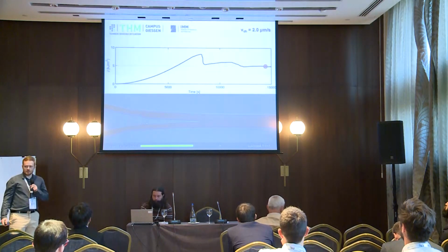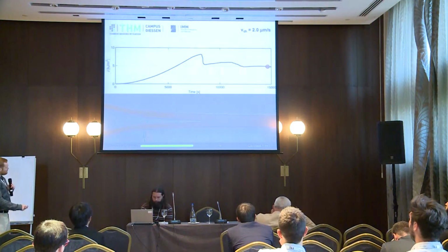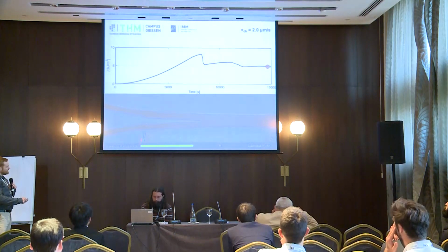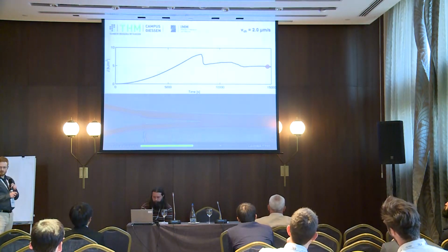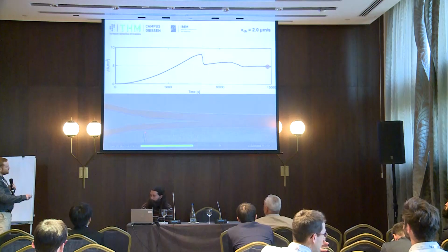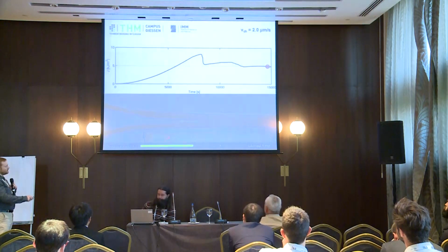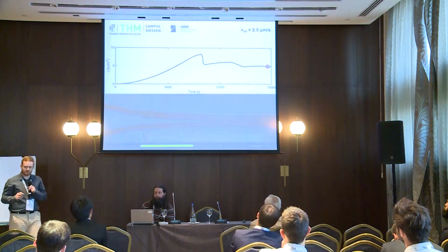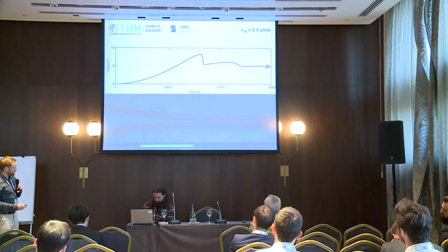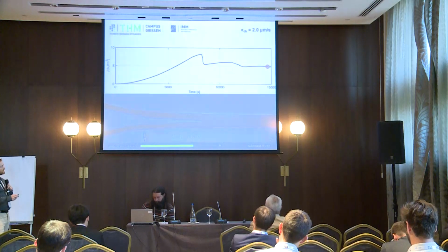And if we look now at the fracture patterns, you see here a very flat area. This was made by inserting the razor blade. And this rough area here is subcritical crack growing from this point to this point. And then the crack jumps and the fracture is near the interface, which is commonly observed for very slow test speeds.